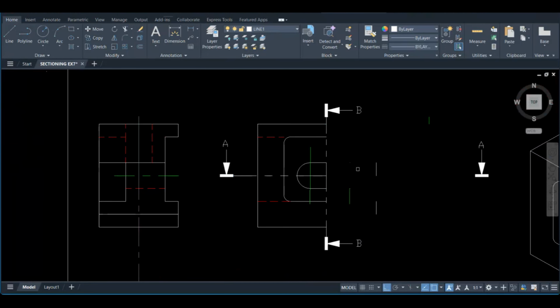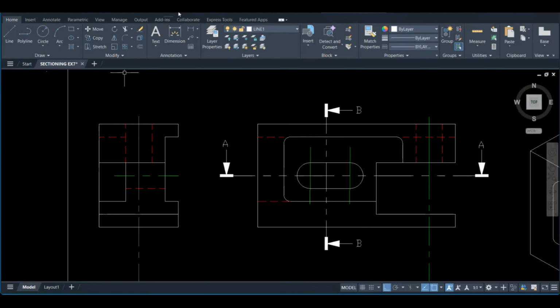Now we're only left with this part over there. From here we could see that this rib should be out. This hidden detail over here is a hidden detail at the back, so we don't have much on it. The same applies to this one. There's a hidden detail here, which is the inside. This one will become a solid line, and this circle is gone. We delete it.